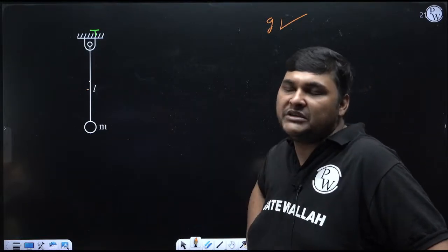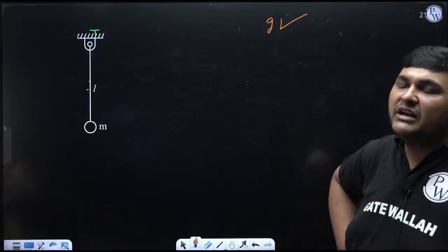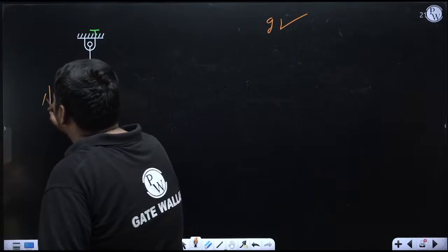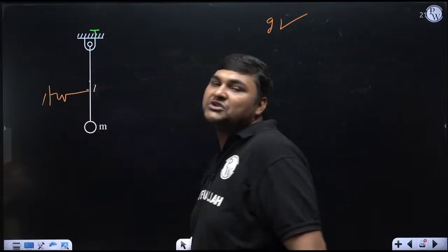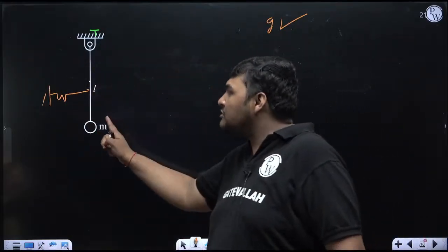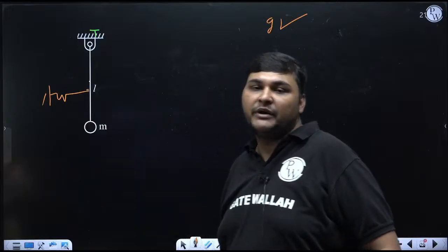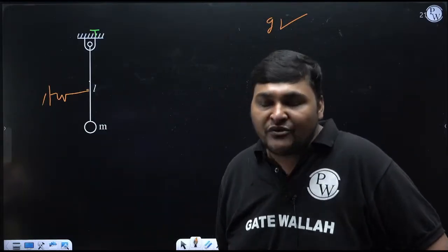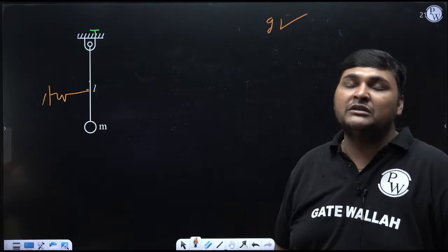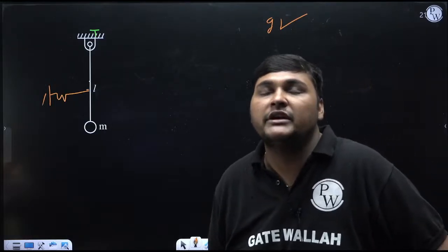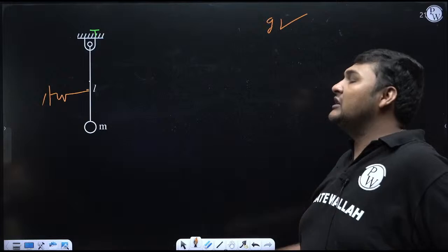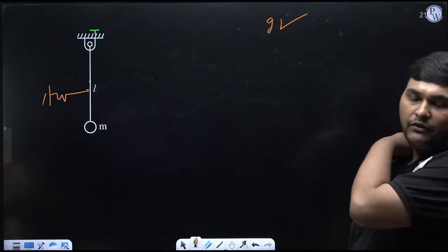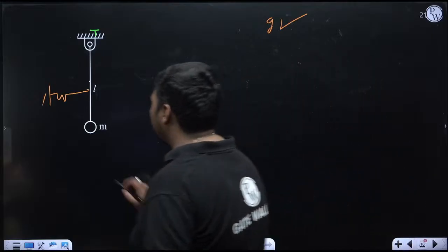Right now the spring is not present, but if I attach a spring, then also due to weight there will be no static deflection in the spring, because the weight of this system is not supported by this spring. So weight will not cancel with the static deflection part. So weight can come into the picture in the equation of vibration, because it is not getting cancelled. So in this type of case, when we derive the equation of vibration, we will consider weight, that is gravity force, also.